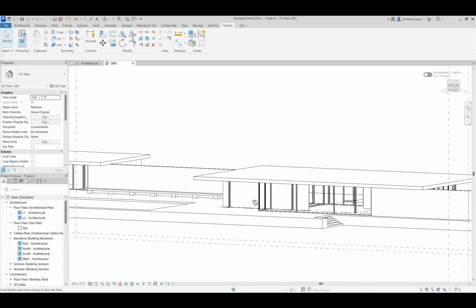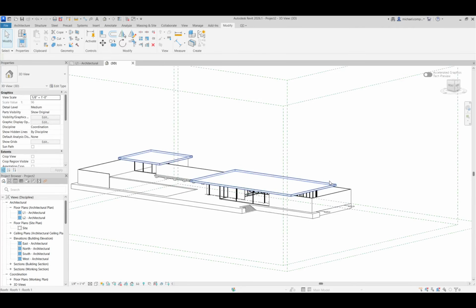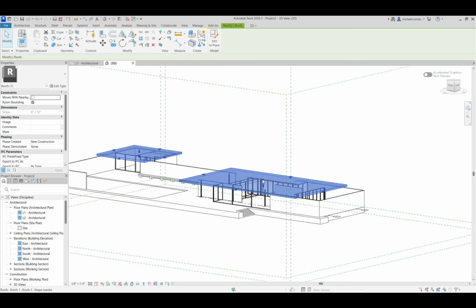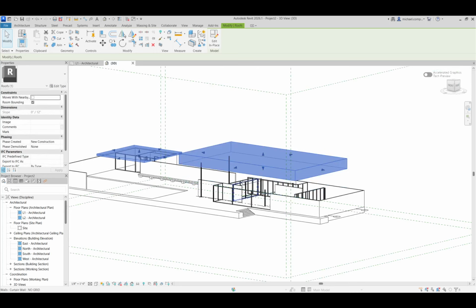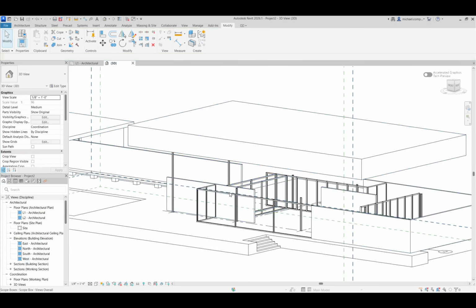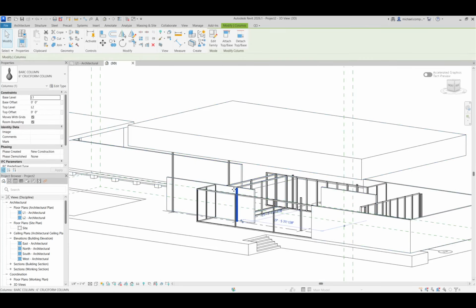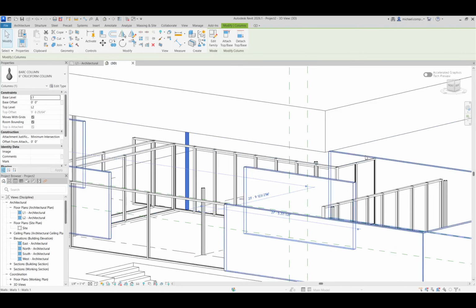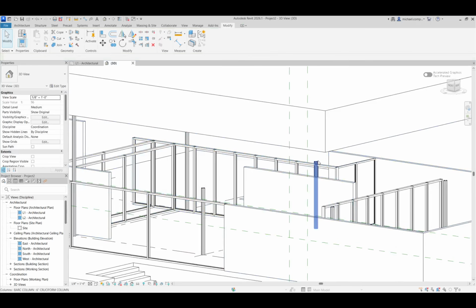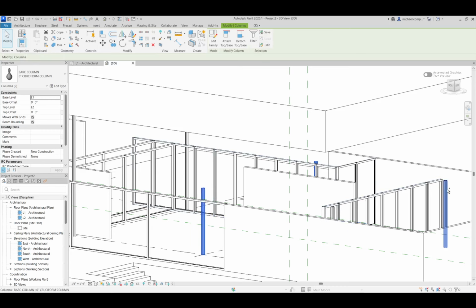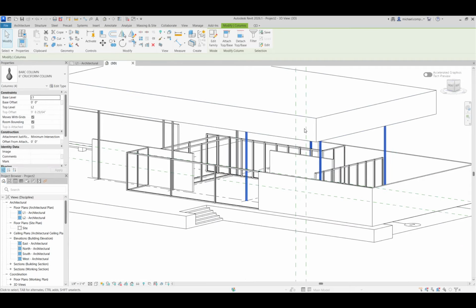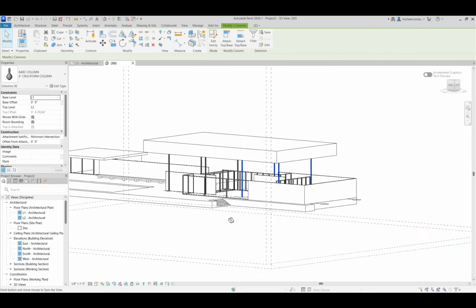So what if I change that roof height? Let's change the roof height. Will the columns come with it? Those did because they were attached, right? You guys see that? So column attach, bing, column attach, bing, and so on and so forth. So anyway, long story short, you can select multiple at a time instead of doing all of them individually. And now those are all attached. So I have them all good.